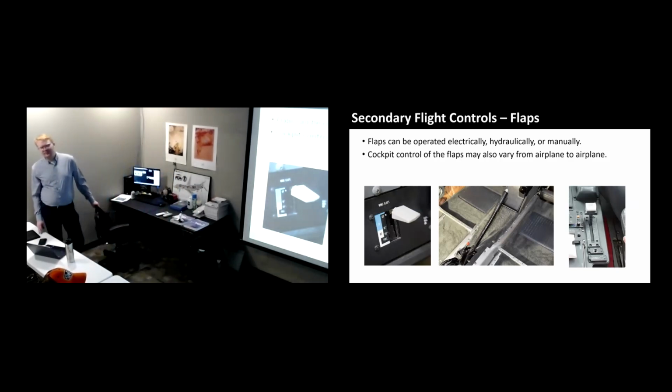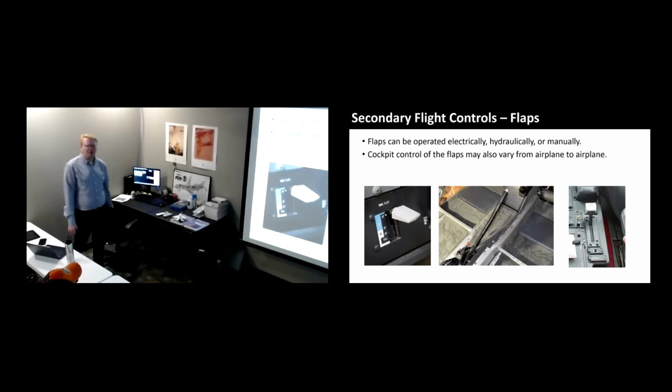So I can see 10 degrees, 20 degrees. What is full, 30 or more? Depending on the manufacturer, usually 30, 35, maybe 40 degrees. Most 172s are in the 30, 35 range. Older models give you the 40-degree flaps.